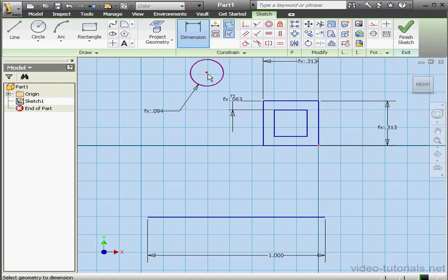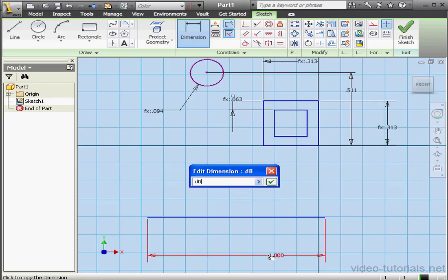Next, we can add 2 more dimensions. I'd like to place this circle in the middle of this square. To do so, we can simply place a diagonal line here and snap the center of the circle to the midpoint of this line. This will work if we only have one cylindrical piece on top of the block. In other words, the smallest Lego block piece, a onesie, as my son calls it. However, once we increase the length and width of the block, that circle will move. So how will we create twosies and foursies?